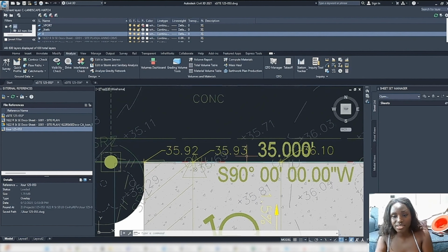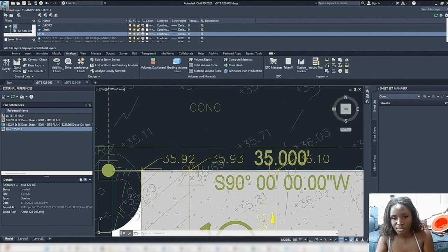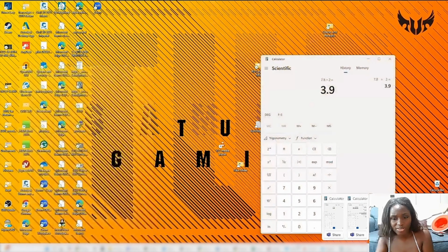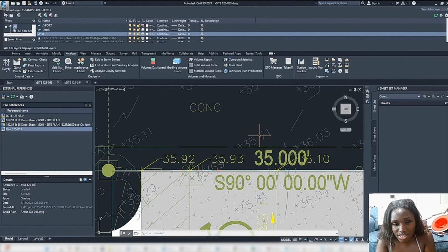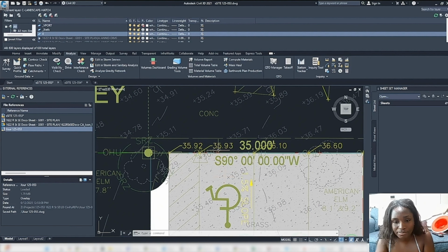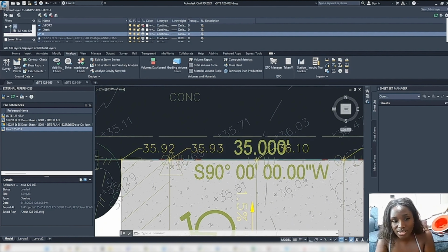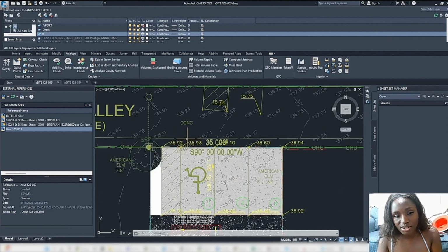So for the ADA parking space, when I first entered that number, it was way too low, which didn't even make sense, so I have a 4.2, which doesn't make sense because here is separate. It needs to be higher. And also, even though this is a much lower number, this needs to be a cross slope of less than 1% because this is an ADA parking space. So as a result, we need to raise it. So when the person does come in, there will be like a 4-inch little bump at the face of the property line so that they can get in.